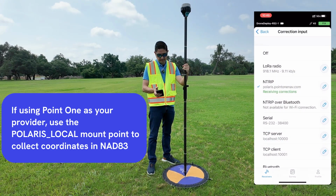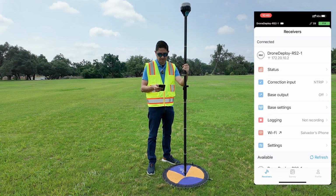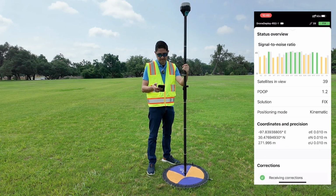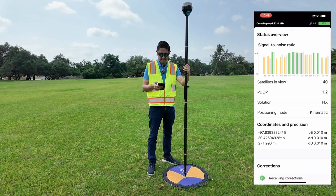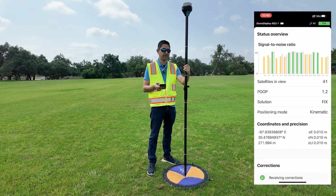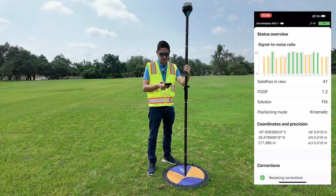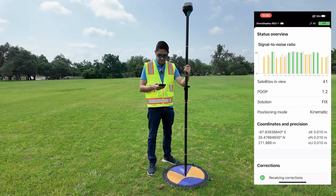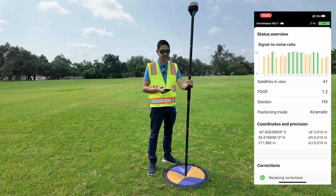Once you input that, the main screen that you have to look at in the Emlid is going to be the status. The status is going to tell you how many satellites you have in reach right now, and if you're receiving corrections or not. The most important thing before you record this is that you have a fix. A fix is not going to be achieved if you're too close to buildings or if you don't have a strong internet connection. Now that we have a fix, we can be confident that the coordinates that we're going to be recording now are going to be precise.